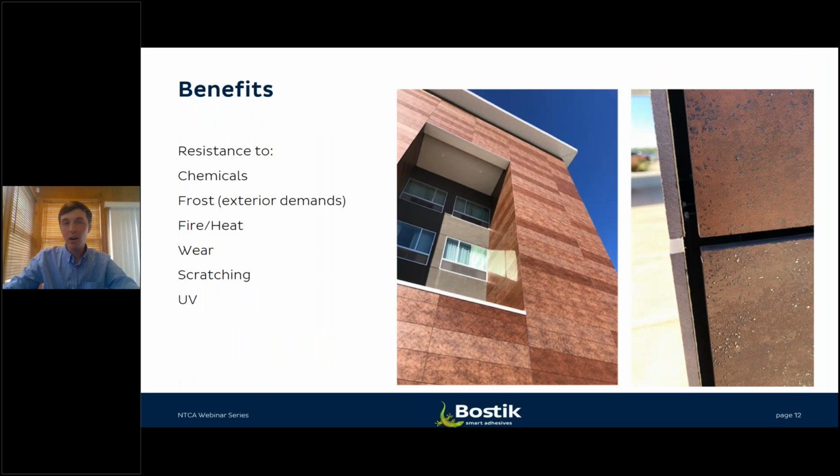So beyond that, they are highly resistant to chemicals. In some cases, the grouts not so much, so there's still a grout selection process that comes into play for gauge porcelain. There's frost resistance that comes into play for exterior applications, fire and heat resistance that is important for applications around fireplaces, direct sunlight exposure, as well as in exteriors on the facade front and paver front.